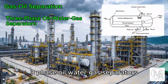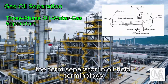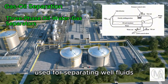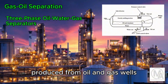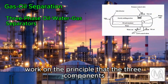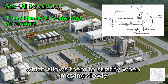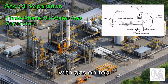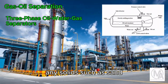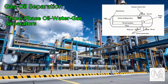Three-phase oil-water-gas separators. The term separator in oilfield terminology designates a pressure vessel used for separating well fluids produced from oil and gas wells into gaseous and liquid components. Separators work on the principle that the three components have different densities, which allows them to stratify when moving slowly, with gas on top, water on the bottom, and oil in the middle. Any solids, such as sand, will also settle in the bottom of the separator.